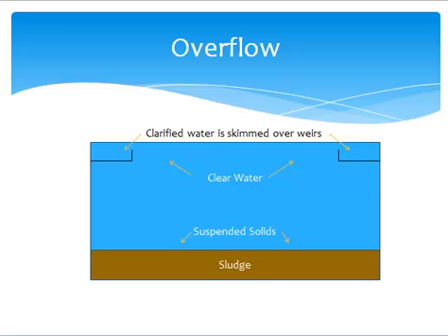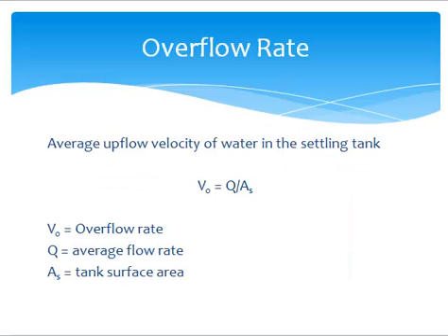The concept of overflow is that suspended particles that settle at a velocity faster than the overflow rate will settle to become sludge. You can see here the formula to calculate overflow rate.